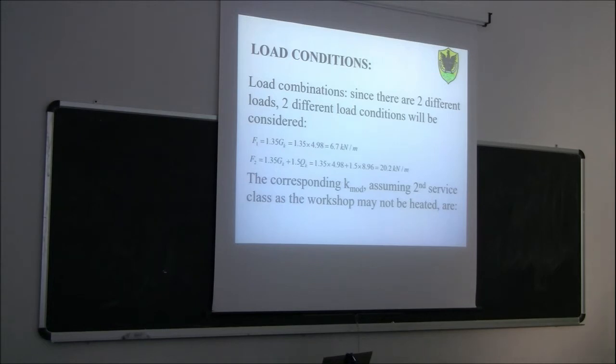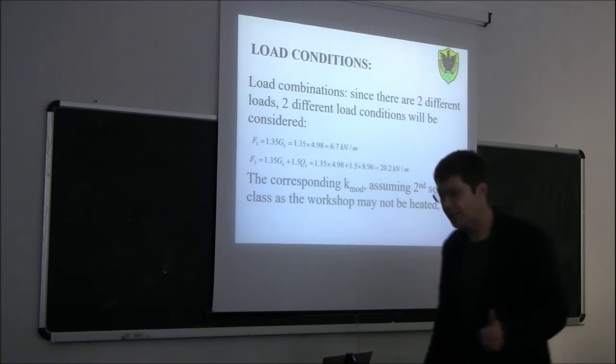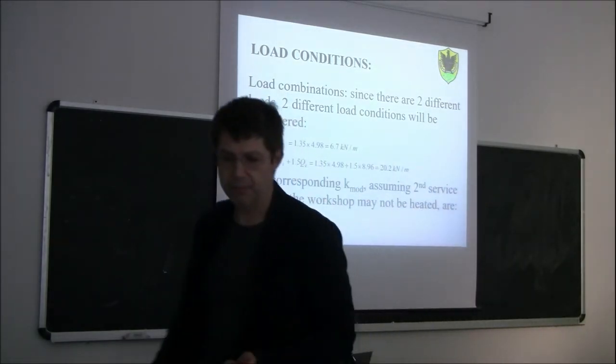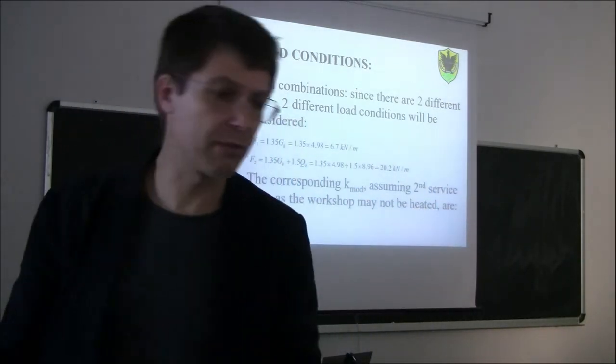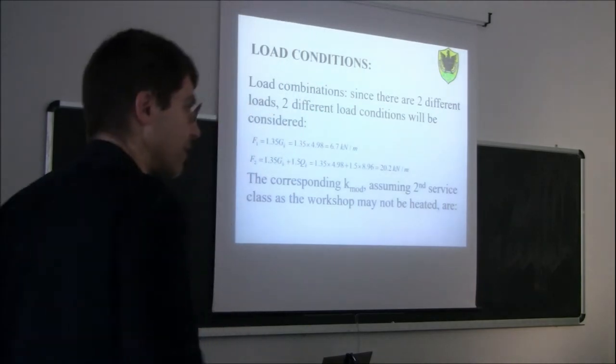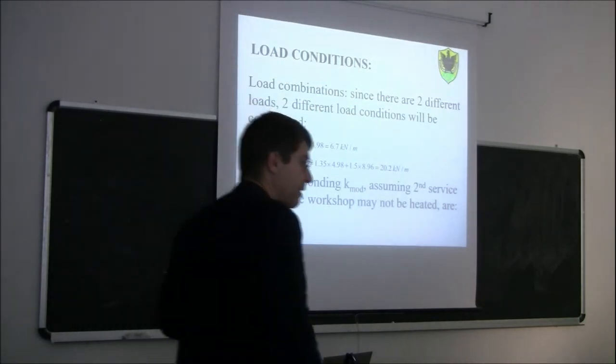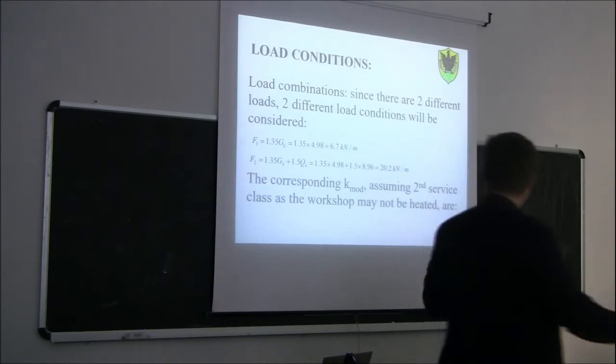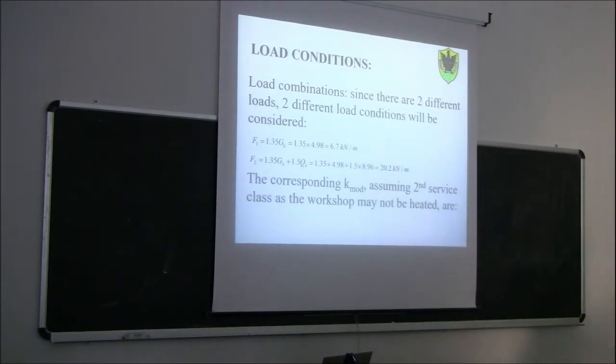Which service class? Because you remember, k mod does not only depend on the load duration class, but it also takes into account the moisture content, so the service class. Now we said that this would be a kind of workshop. And being a workshop, this is not always heated. Very often this is unheated.